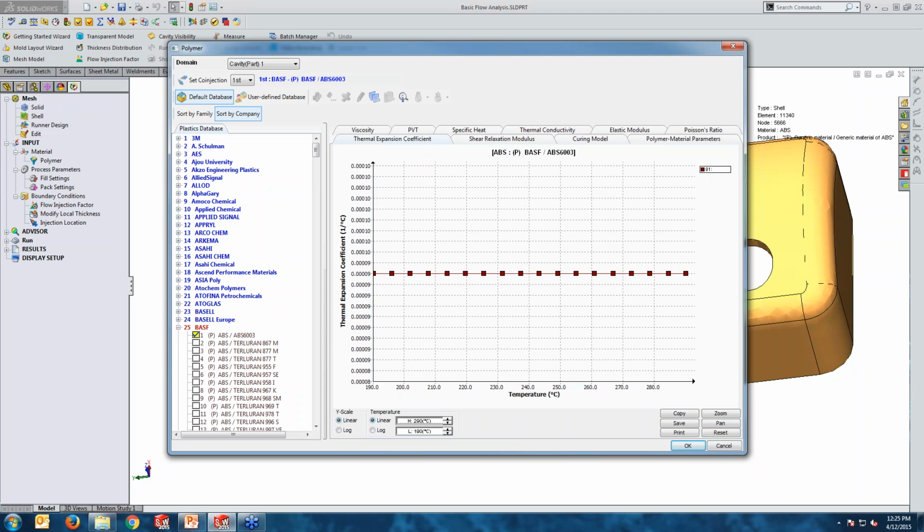This is very good news for those who are really looking at doing an FEA study or a structural test after they've completed the SolidWorks Plastic Simulation. It means, yes, I know it is manufacturable, and now I would like to have a structural test afterward. All the information you need, such as elastic modulus, Poisson ratio, thermal conductivity, specific heat, and so on, is all here. There is no need to go and find the material properties and put them in your FEA studies. That is again a really valuable asset here in SolidWorks Plastics Simulation and can be beneficial directly to itself or to any other cooperative studies.